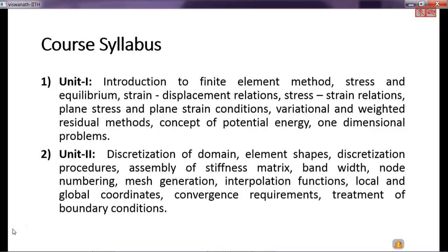But we know that in order to get a simple solution of a bar or a beam, using infinite elements means you are going to spend a lot of time. If I give a problem to the computer and it gives me an answer after 1 year, it is no use. By that time, the product would be released by my rival and they will make profits. So we need to understand what is the real amount of refinement we require. To know that, you need to know that if I double the mesh, how soon I would converge to the exact solution.